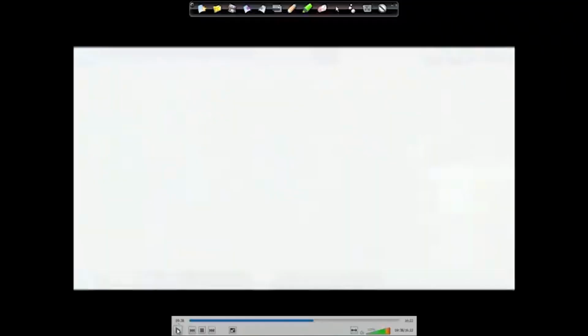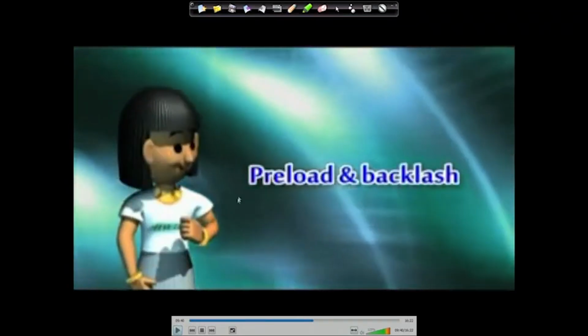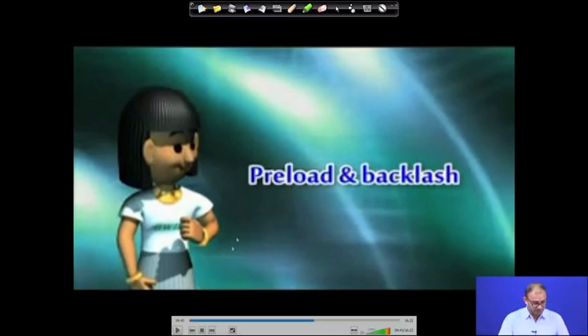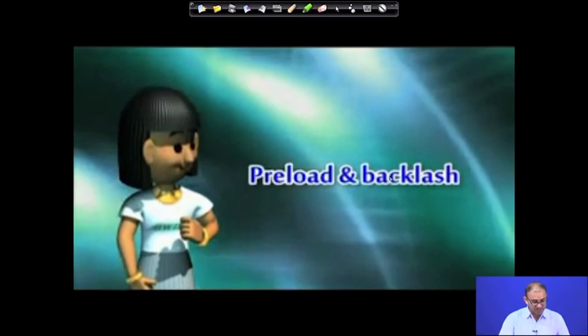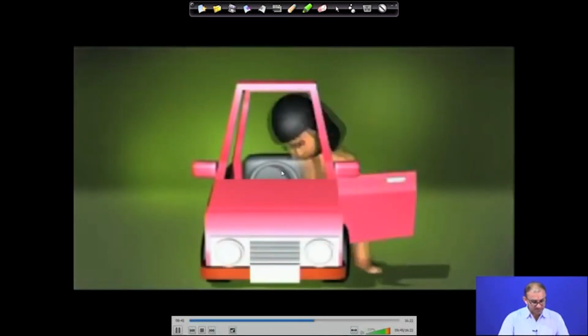In the last class we have seen different definitions: service, rated service life, dynamic capacity and all these things, and there are two terms which are very important in bearing application. One is the preload and another is the backlash. So, let us see how these things play an important role in the bearing or linear guide way design. Now consider this one thing.